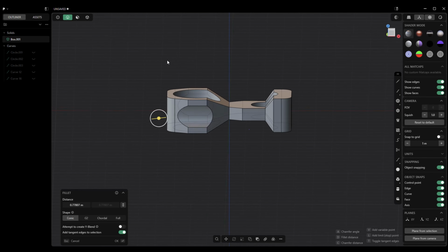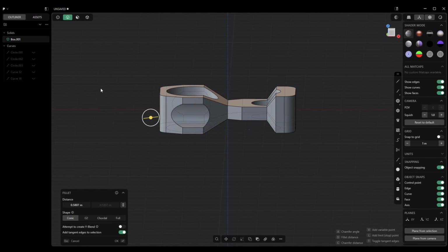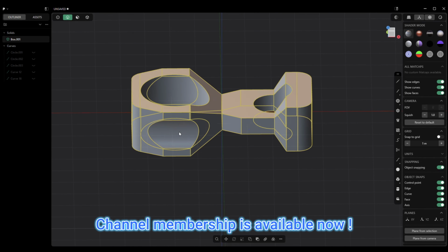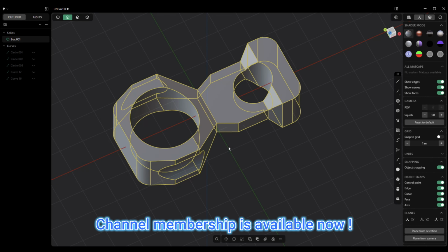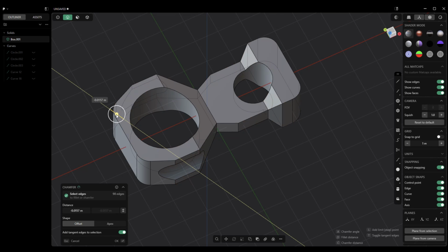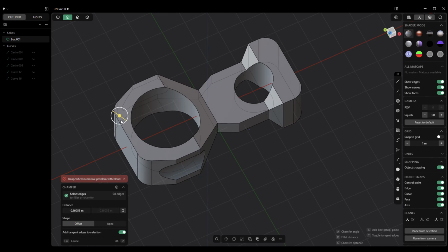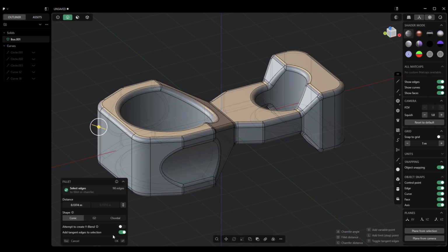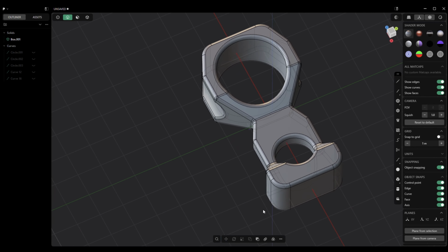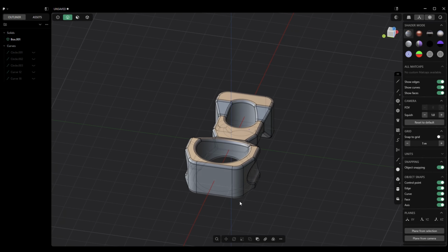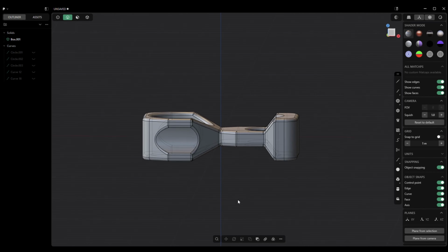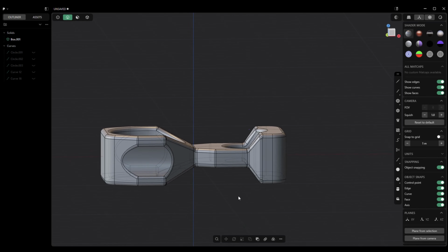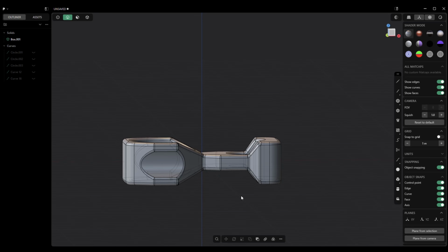Round that over. And then we're going to grab all of this. Click on OK first. Grab all of this and see if we can add a little chamfer to it, right? So we're going to hit B for bevel. There you go. So suddenly you have an object that's way more interesting, right? So the point of this video is really to create a scenario where you are open-minded to the dimensions, right?